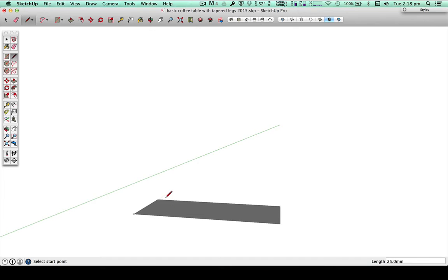If in SketchUp we have made a 2D shape, like we have here a rectangle, where all of the lines making the side connect, then it gives us a solid. Now I can get rid of that solid. I'll just press delete. But let's say I didn't want to do that. I could either press undo, of course, or I can just draw another line on top of one of the existing ones, does no harm, and we've got that line back. So just to deviate there, we are still drawing our first leg. This is the bottom of the leg at 65 millimeters by 25 millimeters. At the moment it's 2D.